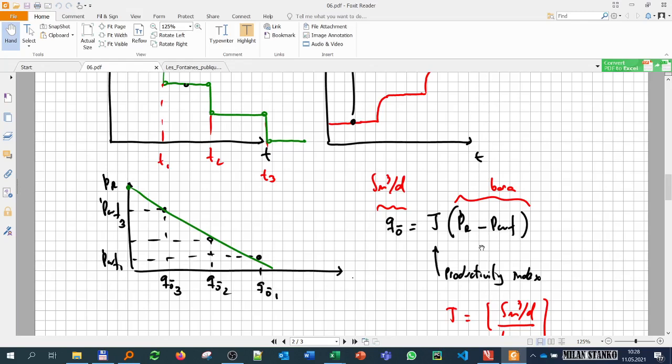But one of the deficiencies is that I need to have a producing well to be able to know the J. Another problem is that, for the design phase, we don't have the well yet, so we cannot make any testing and see how it behaves. For planning and design of the well, we're interested to see what's actually affecting this J, and how I can make it larger, because I'm interested in maximizing the production. I also need to know future performance, what will happen with that curve in time. So I need to make sure what's affecting that and how it can change in the future.